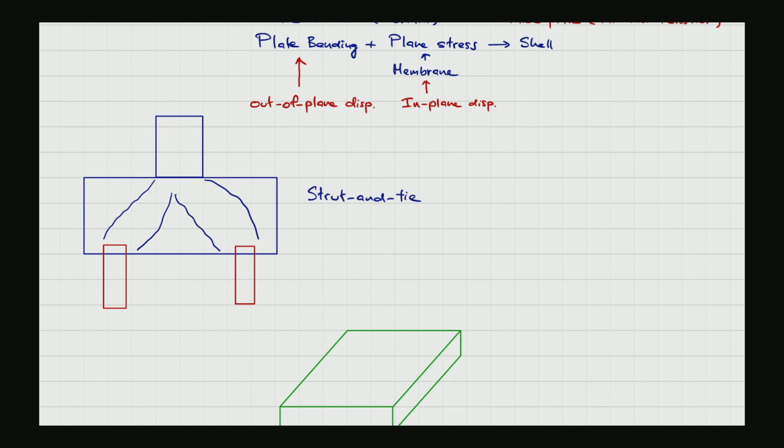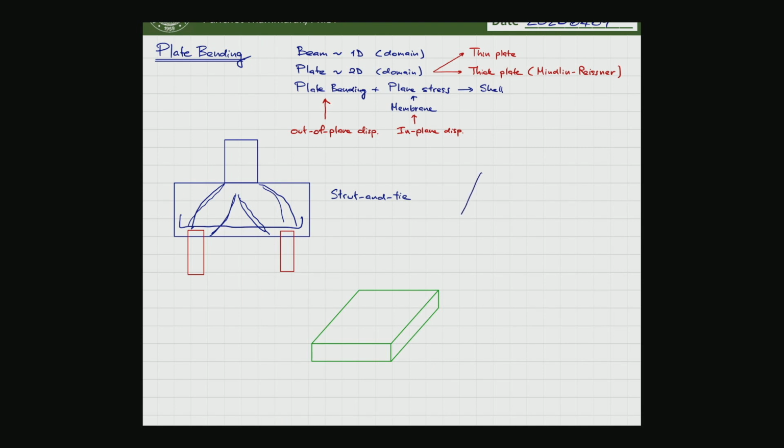So we have strut and tie model forms. You have the steel tie, and you have the compression strut from concrete. You do not have the bending like we derived in the Timoshenko beam. You have two sides of the beam with the given rotations. These are used along with the cross-sectional rigidity of the beam, EI, to get the moment, and then the shear deformation is computed accordingly.